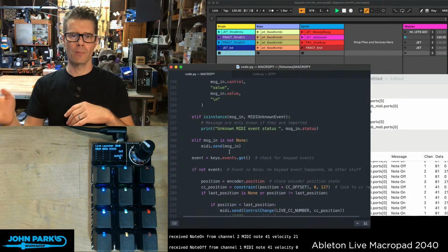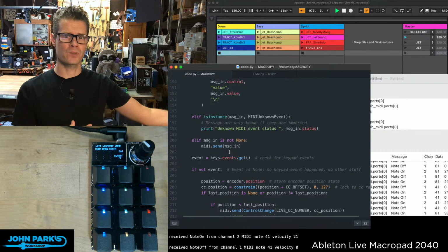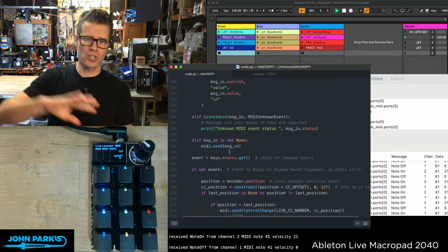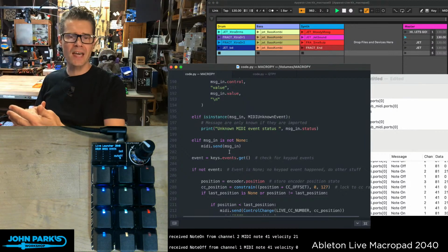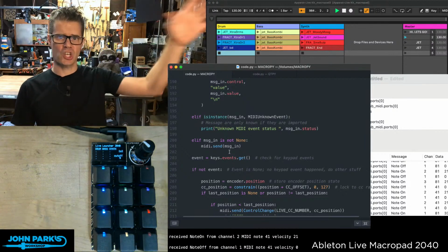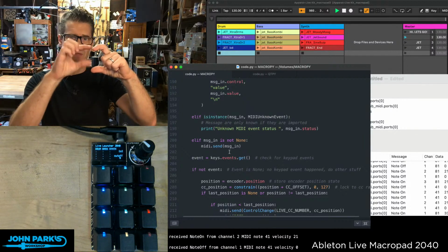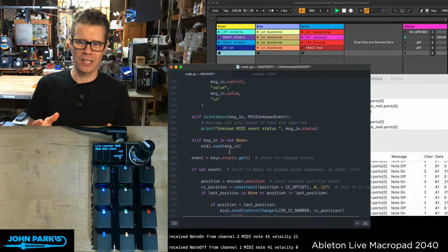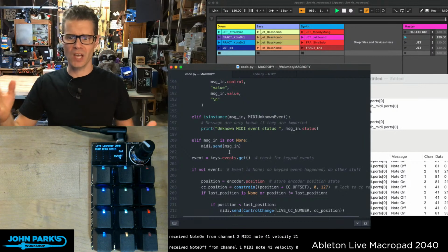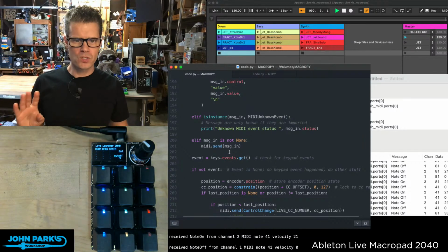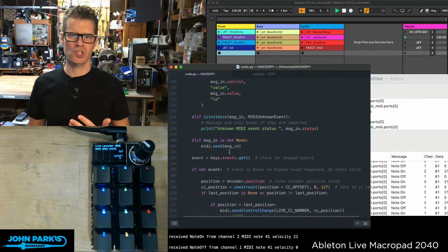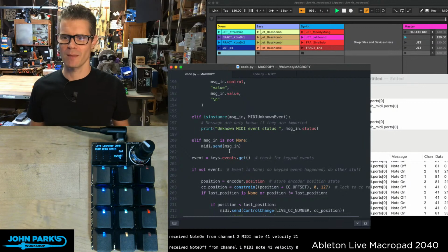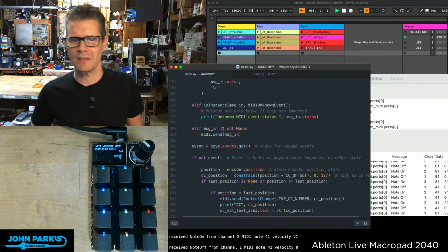It's anything from one machine telling another that they're syncing up their clocks so they stay in time, to having a controller tell a synthesizer to switch to a different preset, to, like I said, showing a little text on a display. So this is not actually really an off-label use of MIDI. This is kind of what it was made for. Somewhat funny to see note-on messages and velocities used to say colors and channels used to say which animations, but not strictly forbidden, I don't believe.